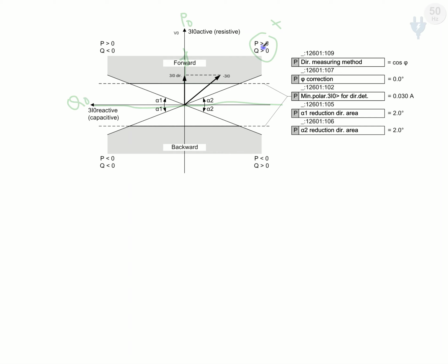But these ones are for the real, for the positive sequence power, because in this axis here becomes P and here becomes Q. We tilted the zero sequence power by 90 degrees, because this V0 mostly occurs at 90 degrees of the positive sequence voltage. And in another component, this direction is backward and this is the forward direction.